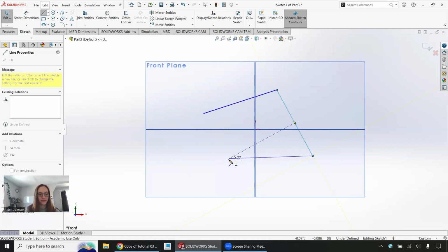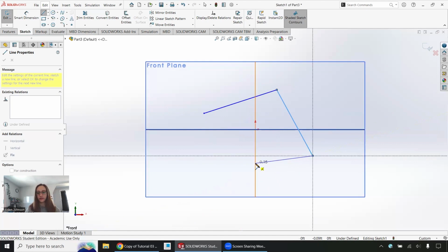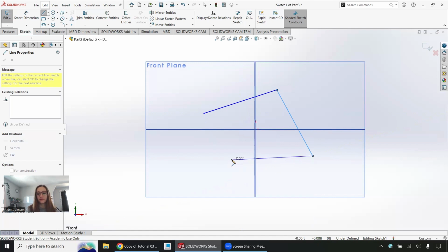As I continue my shape, you can see that it has some other suggestions for me as well. It asks if I want to align my endpoints, make something parallel, or let's see if I can get it to suggest perpendicular right there. It may suggest that I intersect with this plane as well, but I want to opt out of all of these. You always want to be mindful of if you accept or reject these suggested constraints.